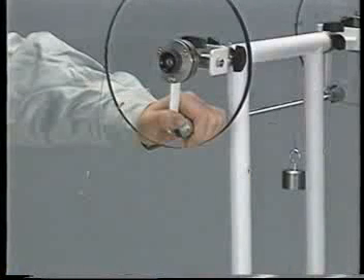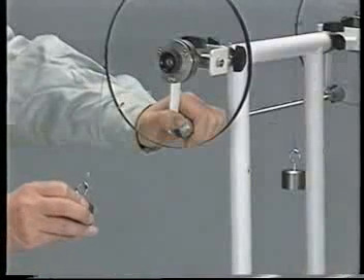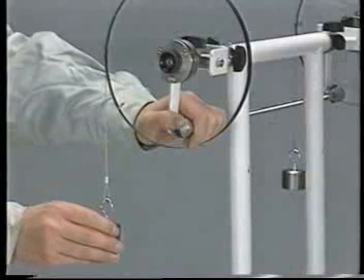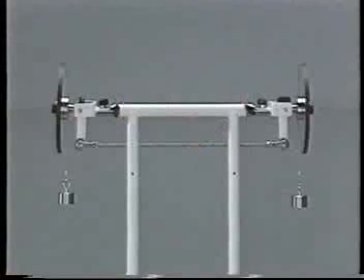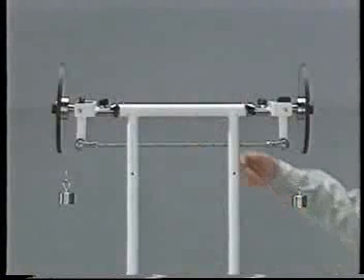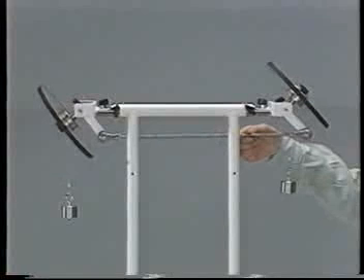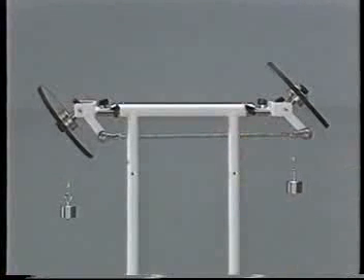In this experiment, the model stands vertically and the wheels are secured so they do not rotate. Weights equivalent to the friction are attached. First, the caster angle is 0. Turn the steering wheel. As you can see, after the wheel is turned, the wheels remain in the position they were turned out.